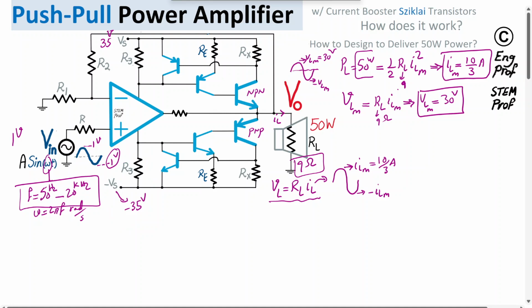I can say as a result, the op amp is with proper bias, and as I mentioned earlier, from the output via this wire going back to the negative terminal, as I explained, it feels like a negative feedback. So the op amp with proper bias and negative feedback is in the linear region, not saturated, and because of negative feedback, it enforces a virtual short for the op amp operating in the linear region, which means the voltage of the positive terminal is equal to the voltage of the negative terminal.